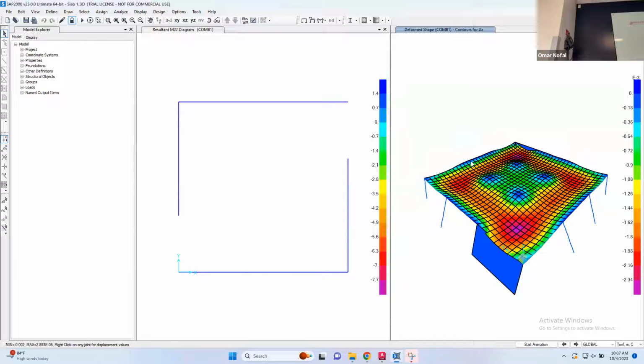So in my model, these shear walls and these columns are supported by the slab on the support up there. So I didn't remove the supports that I have from up there, and I didn't bring them down. What I have to do is remove the hinges that I put here, and put hinges at the columns, right? Because the columns are the ones who support the slab. So I need to remove all the supports that I defined in my previous model. So let me unlock the model.